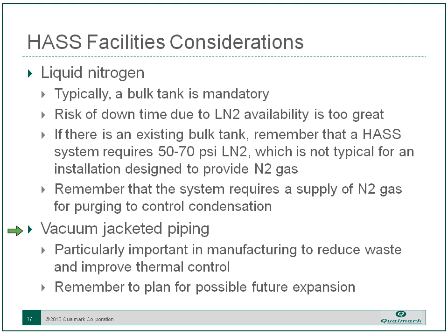Number 1, you'll get nitrogen that has fewer bubbles in it. Anytime nitrogen warms up a little bit, it makes bubbles. When it gets bubbles, it confuses the control system. And with the control system confused, you wind up using more liquid nitrogen. And the other thing, of course, is that liquid nitrogen is expensive, and when it evaporates, it's wasted. So anywhere you're making frost, you are wasting money. And then that frost will promptly turn into water during the night, producing slip hazards in the morning. So vacuum jacketed piping will take care of a lot of that.